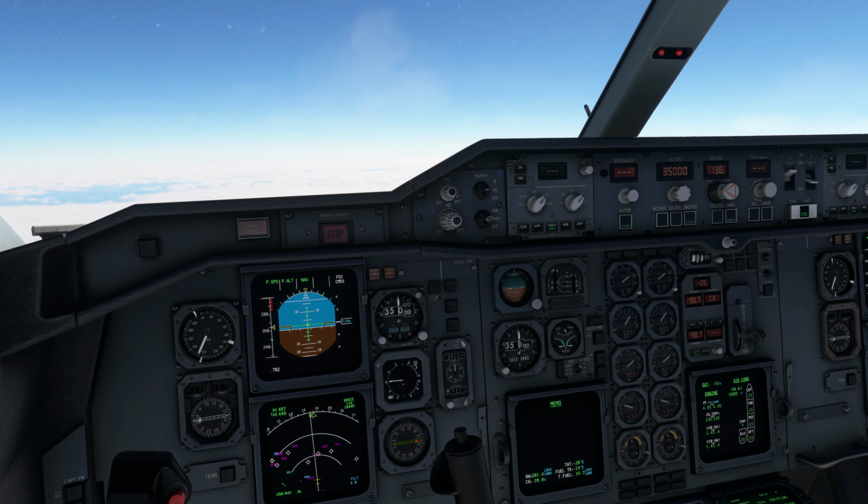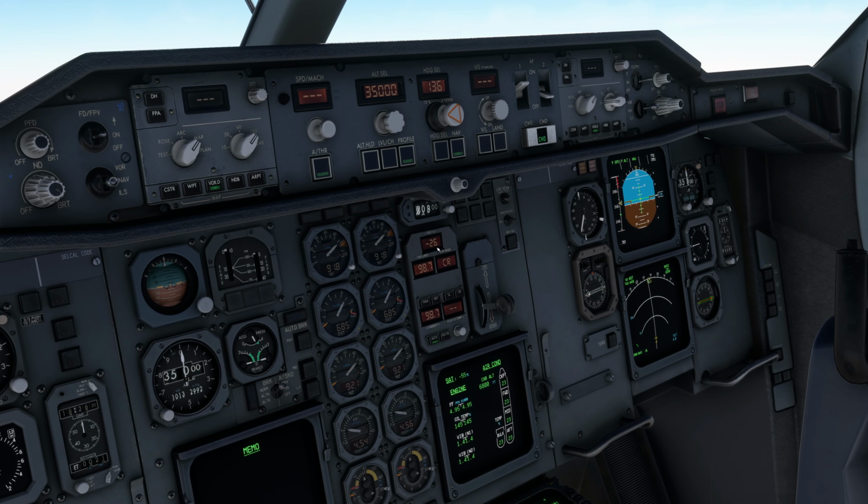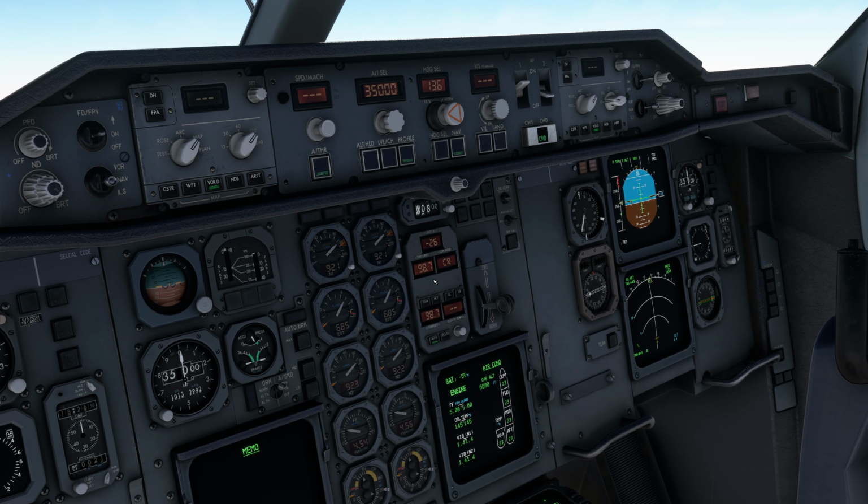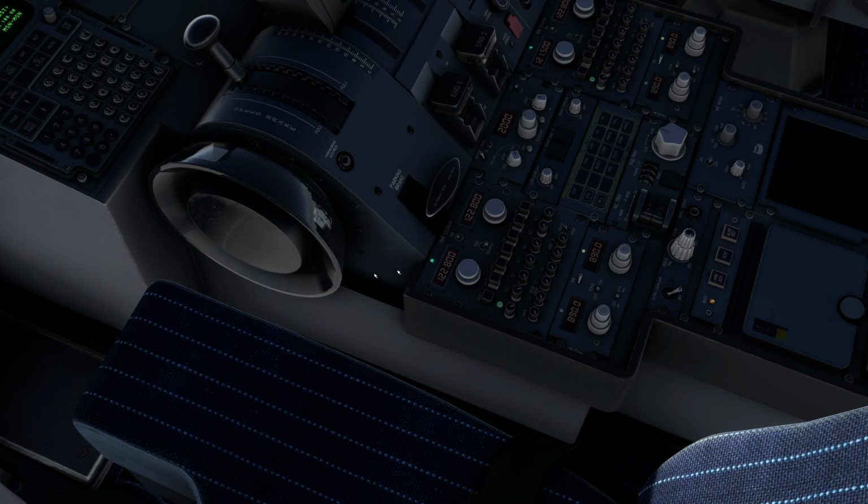I'm Emmanuel, I'm an Airbus pilot, and in today's video let's have a look at the cruise procedures for the Airbus A300 from iniBuilds. The first thing that we do when reaching the cruising altitude is verifying that the thrust mode went into the correct mode, so it's in CR, and then we're going to go down to the TCAS and select the below mode.